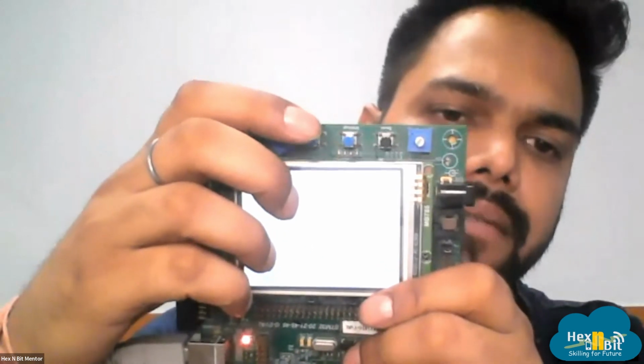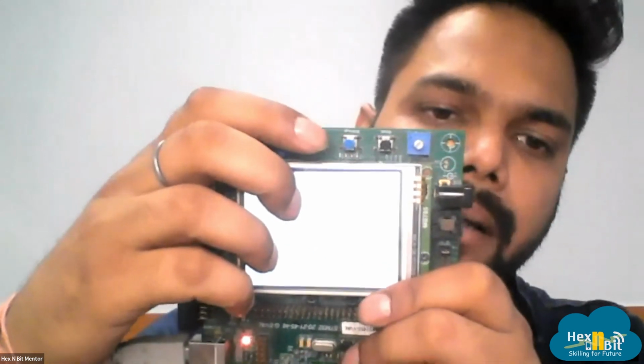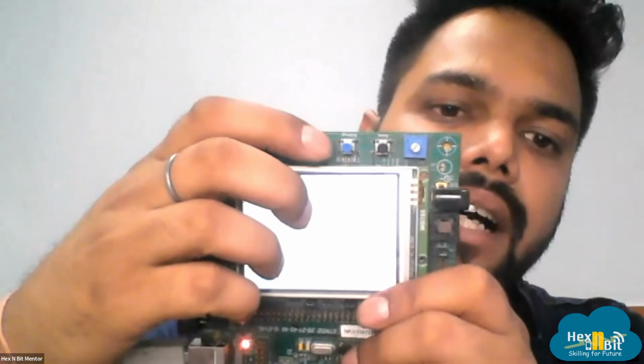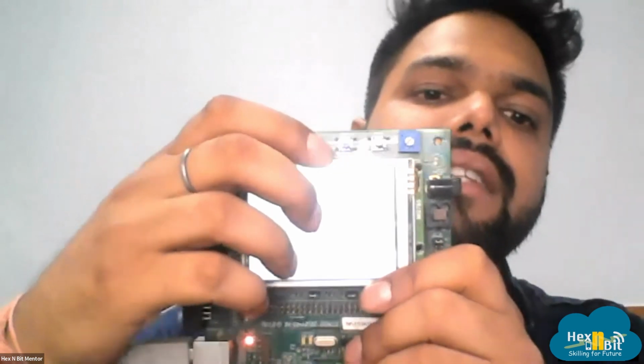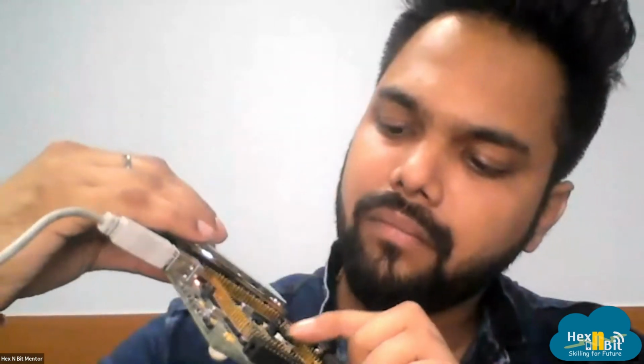Okay, so we're going to have this small activity of LED blinking. These four LEDs, at the bottom of this button, are connected to the controller on predefined pins. For example, LED1 is connected to PG6, LED2 is connected to PG8, LED3 is connected to PI9. So what we're going to do is select that pin.